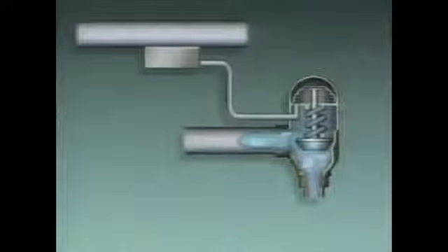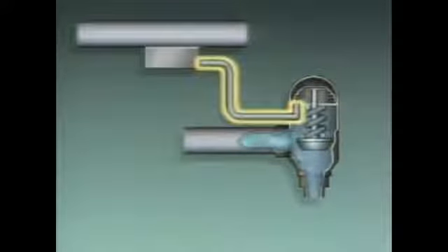In many systems, refrigerant flow, and therefore the amount of cooling, is controlled by an expansion valve. The position of the expansion valve is controlled by the temperature of the substance being cooled. Some control systems use a thermostat located in the area being cooled to position the expansion valve. Other systems may use a thermal bulb or a thermocouple. We'll use an expansion valve and a thermal bulb to see one way to control the amount of cooling that a refrigeration system provides. This illustration shows the expansion valve, the thermal bulb, and connecting tubing.